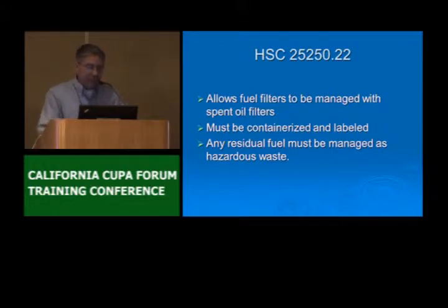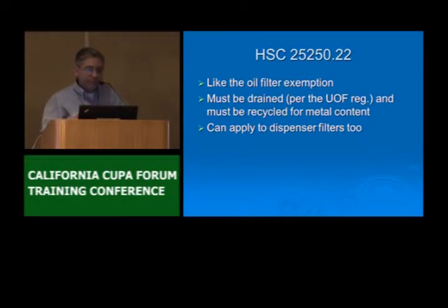When you do that, you have to containerize and label the filters, and you have to include on the label that the container contains fuel filters. Any residual fuel must be managed as a hazardous waste. So under the oil filter regulation, the oil that collects in the bottom of the oil filter drum has to get collected and be managed as used oil. Here, if you have fuel that's collecting in the bottom of the drum, it has to be managed as a hazardous waste. Like the oil filter regulation, the fuel filter statute says the filter must be drained, okay? And it must be recycled for its metal content, okay?